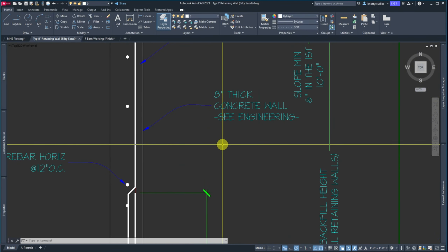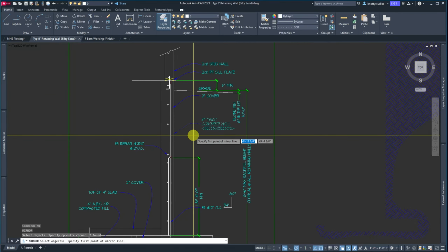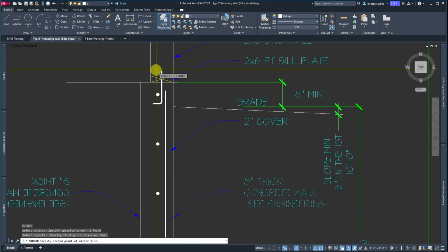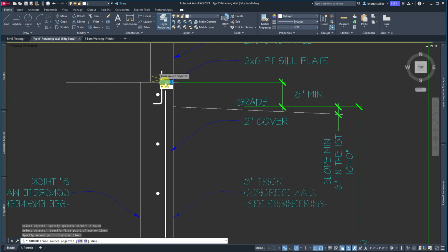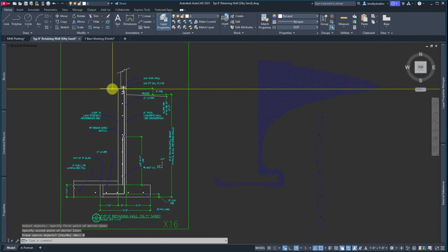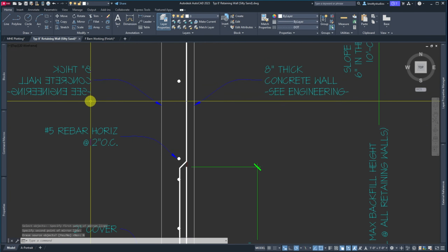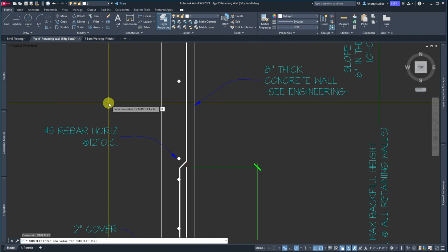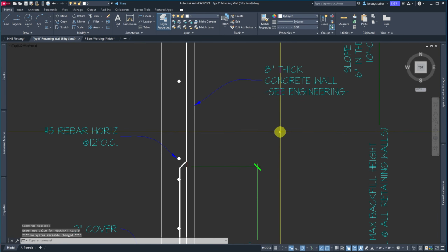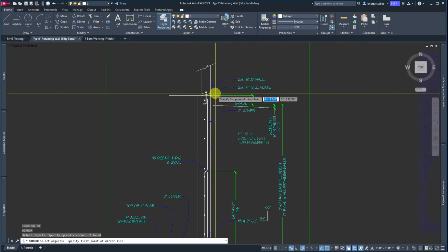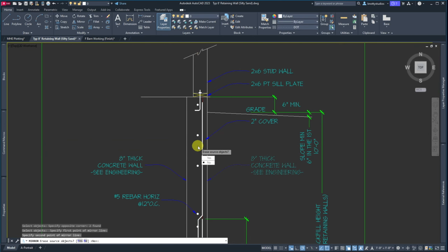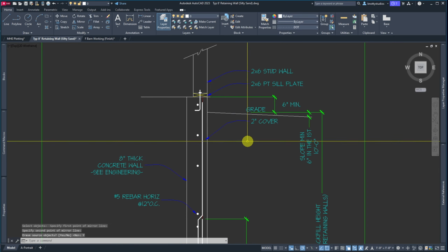Now, this mirror is not going to work perfectly. So I'm going to mirror this about the middle of this line. I want to bring it across. See the text? Yeah, well, let's just say no. We're just going to erase that one anyway. It's backwards. Well, what's causing that is MIRRTEXT. There it is. Set that to 0. Enter. Now, mirror that about that. Come down. And yes. Now I've got some room to work over here.